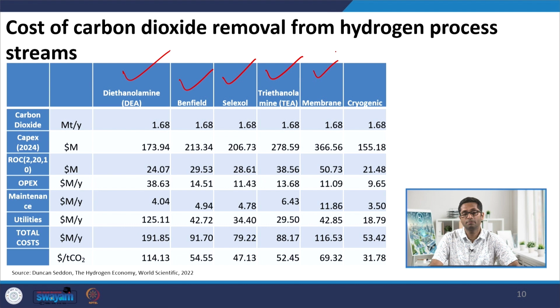So when I say membrane based technologies, I am looking towards membranes which are selective to the passage of carbon dioxide. So what is happening is whenever we have high pressure gas coming in, the membranes are selective to the passage of CO2 such that it passes the membrane and goes towards the low pressure side, and a concentrated stream of CO2 could be produced, whereas on the high pressure side you would have a CO2 depleted gas that is available.